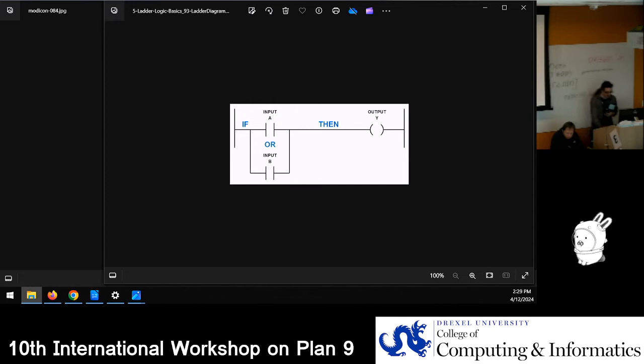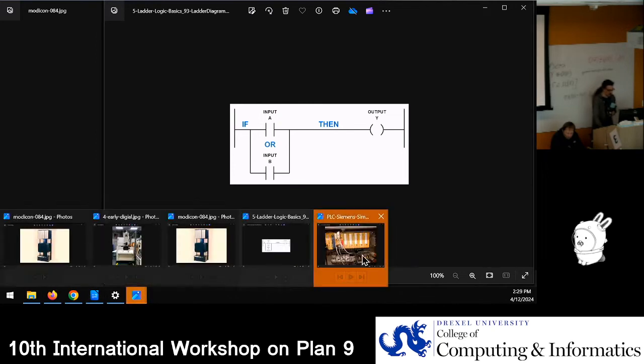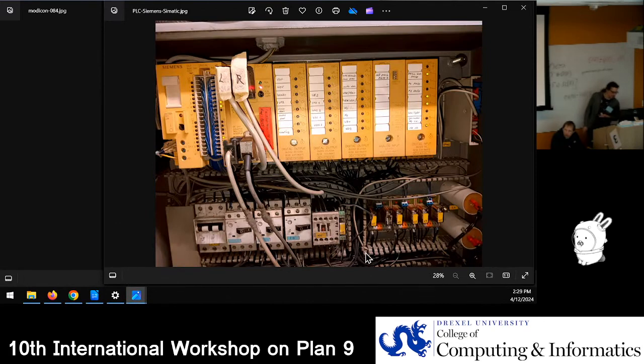So over the years, this created a divergence in thinking about how computing works, and it went in the direction of the discrete PLC. A more modern discrete PLC would be something like this, which is a Siemens Simatic, and this is actually inside of a machine at my work. As you can see, the processor is on the left, and then you have these I/O expansion modules: analog inputs, digital outputs, and so on. These are all connected to sensors and switches on the glove box that monitor pressure, doors open, and control pressure solenoids that let gas into the box.